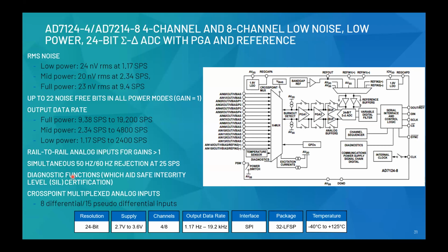The part can do 2.7 to 3.6 volts, so a lot of battery type of applications also can be solved with this particular ADC, and it supports the popular SPI interface, with which you can have any microcontroller talk to it.